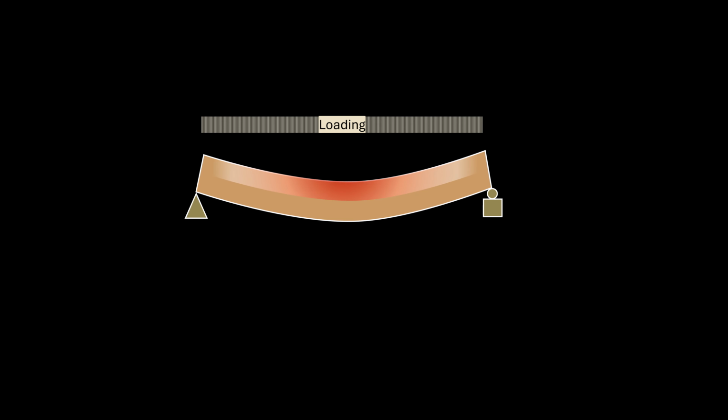Bending moments are the internal forces that cause a structural element like a joist to bend under applied transverse loads. These moments create a curvature in the beam resulting from compression and tensional forces across a cross-section. When a member is in bending as shown, the upper part of the beam experiences compressive force while the bottom part is in tension. The line between the tension section and the compression section is known as the neutral axis.